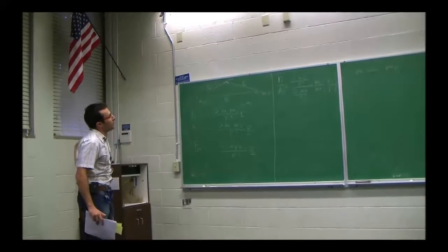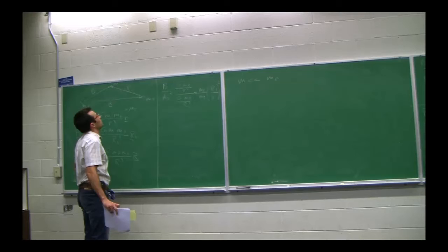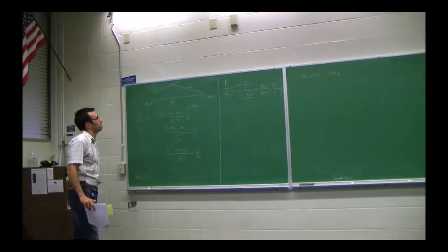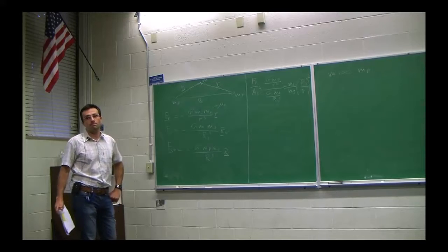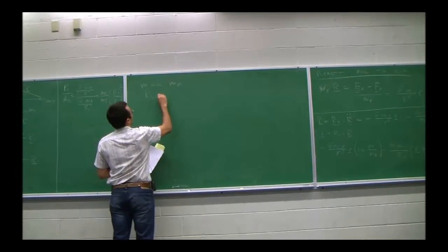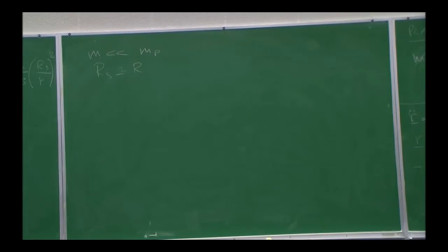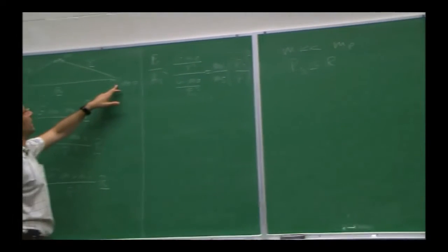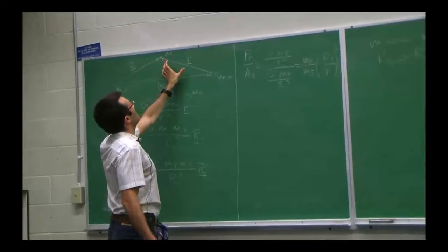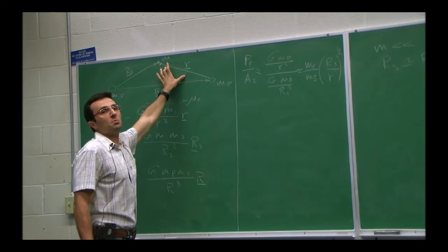What I want to compute is this sphere of influence, which I don't know how big it is, but my feeling is it's probably going to be pretty small compared to the distance between planet and the sun, right? That's my idea. And so, can I say this? I think I can. In other words, if I am inside this sphere of influence, meaning I still am looking at the motion of the object from the point of view of the planet, because I'm not that far away, I'm not in a heliocentric orbit, this distance here, this vector little r, which we have dealt with for a long time at this point, is probably going to be very small.